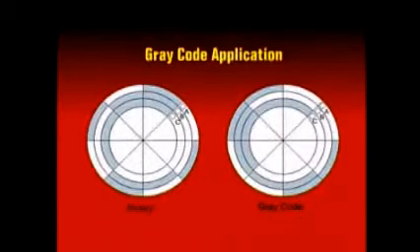As the disk rotates, the brushes come in contact with the conducting area and the insulated area. The 3 LEDs display the position of the rotating shaft in terms of 3-bit numbers. Consider the disk on the left. If the disk on the left rotates in the anti-clockwise direction by 45 degrees, the brush A comes in contact with the non-conducting strip. Thus, LED connected to brush B lights up indicating binary 010.